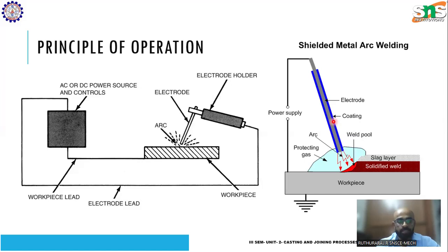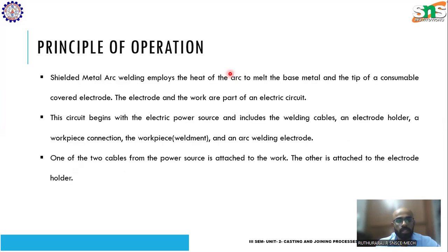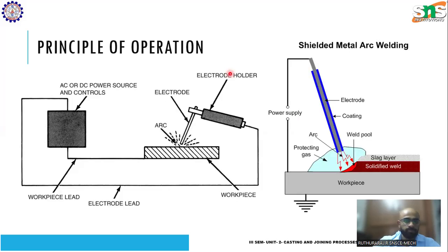Then, getting to the next thing, what happens during the welding process is that the metal is melted, the filler rod provides excess material, and then they are joined together once it solidifies. Gas welding equipment can be used for both cutting as well as joining. But the arc welding equipment can only be used for joining, because it cannot be used for cutting, because the electrode is a consumable electrode. That is one of the major differences between gas welding and arc welding.